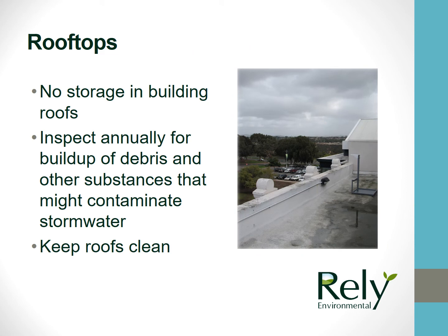Rooftops must be cleared due to rain events. Materials are not to be stored on building roofs. The rooftop must be inspected annually for buildup of debris and any other substance that might contaminate stormwater. Keep in mind that a clean roof is important for prevention of stormwater pollution.